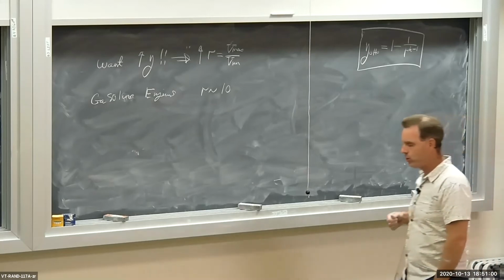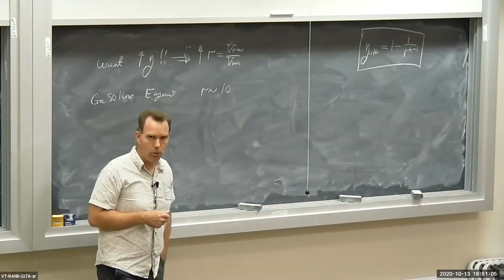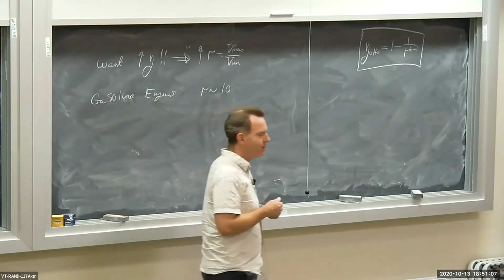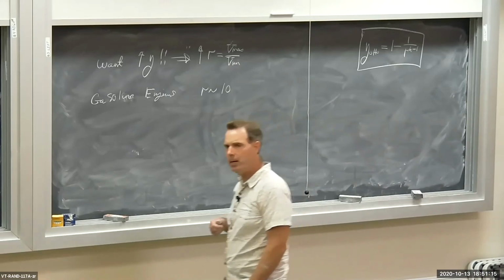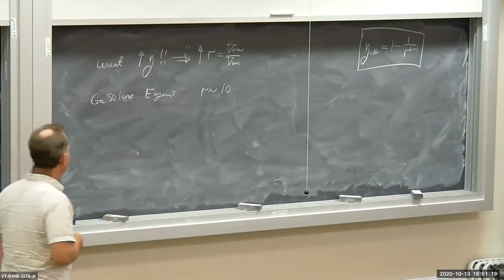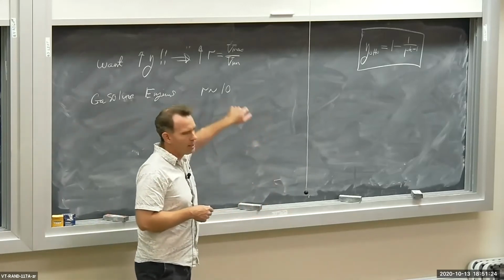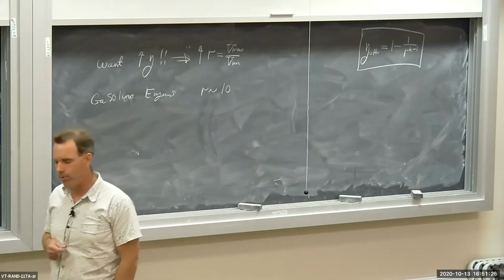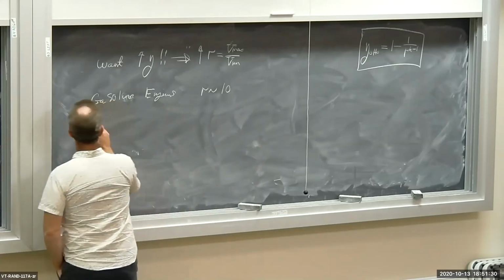High performance engines that can run on a high octane fuel. High octane fuel is better for high compression ratio engines, about 12 or so. Okay, it tops out at about 11 or 12. Now you might ask yourself, why are we stuck at around 10, 11, 12 for a compression ratio? Well, note,